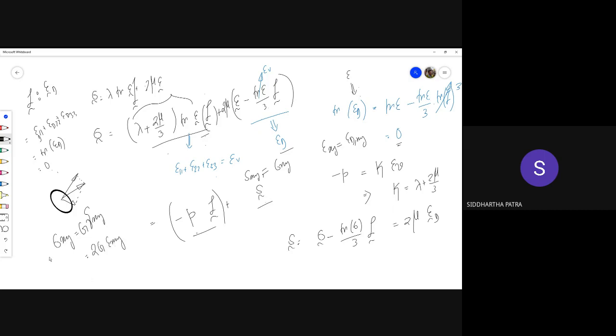Since S xy is also this quantity, and this thing is also epsilon d xy, that only goes to show you that G is essentially mu. So this is the relationship between shear modulus and mu, and this is the relationship between bulk modulus and the Lame parameters.